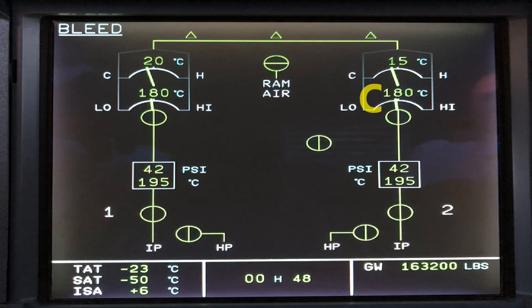Okay, so I just broke down the components and where they are located. I just broke them out. Think about it in broad strokes: there are components related to the engine bleed air system or supply, then you also have the components having to do with the APU bleed air supply, and lastly you have the cross bleed system, in which case we have a cross bleed valve.